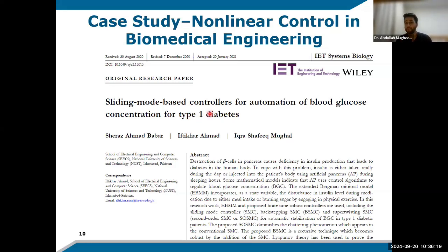Okay. So it keeps on deciding, okay, now give this much amount for this much duration. Next day, give this much amount. It keeps on giving you new information based on the level of glucose in your blood. So it keeps on getting feedback from the system as well, and it keeps on giving you updated decisions based on the behavior of the system.